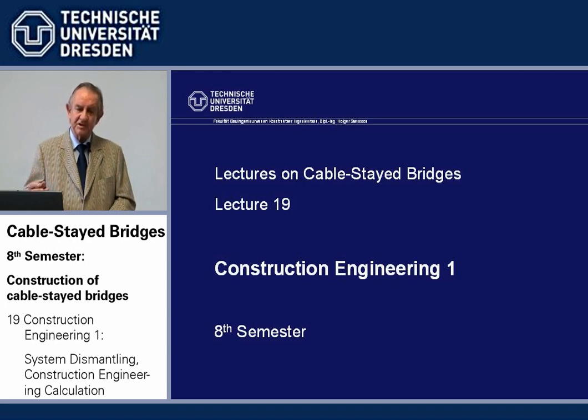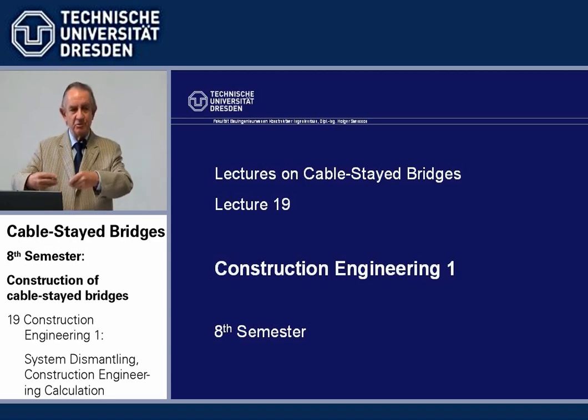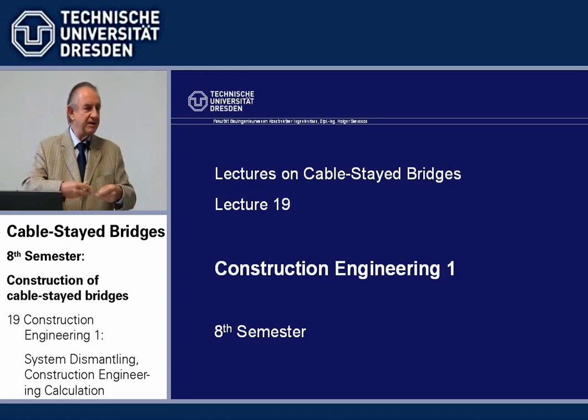So, once we have the bridge designed, we have it sized for the final stage. The amount of post-tensioning, say, or the plate thickness for a steel girder is given. And now we must have a trade-off between straightforward, easy construction methods, which may require additional strengthening only during construction, because these simple methods may put more strain on a bridge than in the final stage.